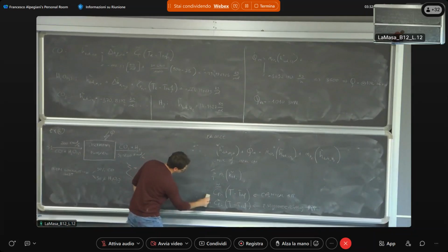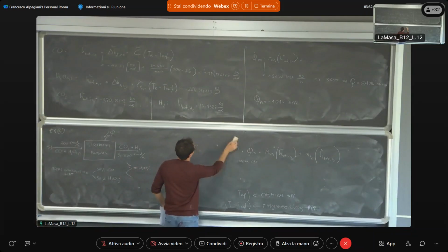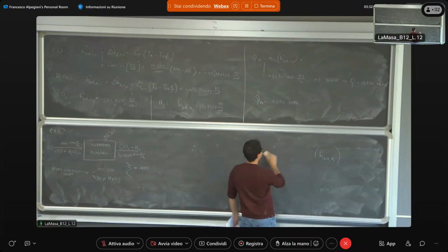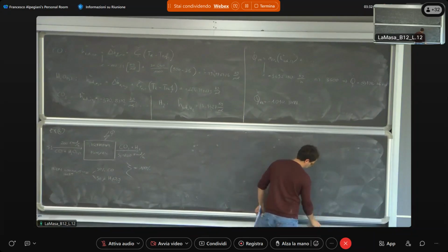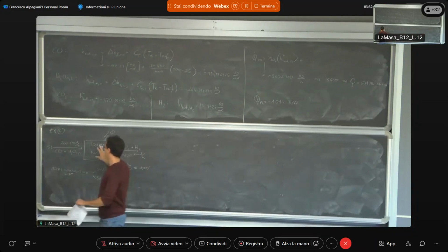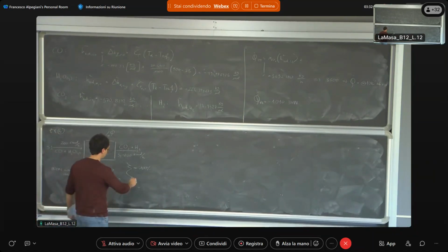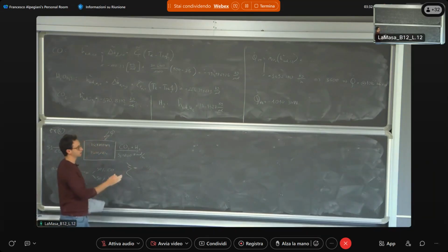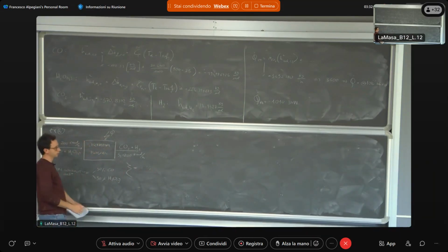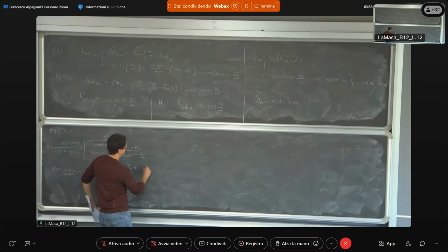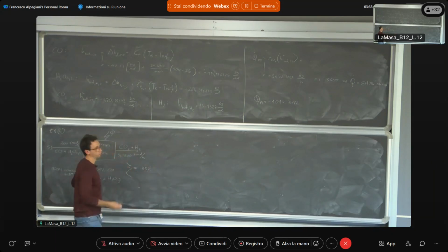So what you obtain in case you have a conversion efficiency lower than 100%, that is what happens in reality, because at this temperature, in a water gas shift reactor at 500 degrees Celsius, you don't reach 100% conversion. In reality, we obtain more or less 60% of conversion. So the chemical equilibrium is a condition in which you have a conversion efficiency of 60%. Now, the problem gives a conversion efficiency of 85%.